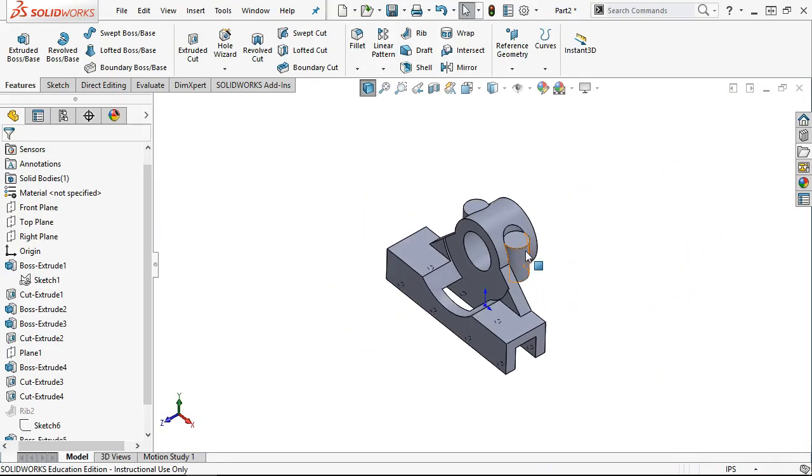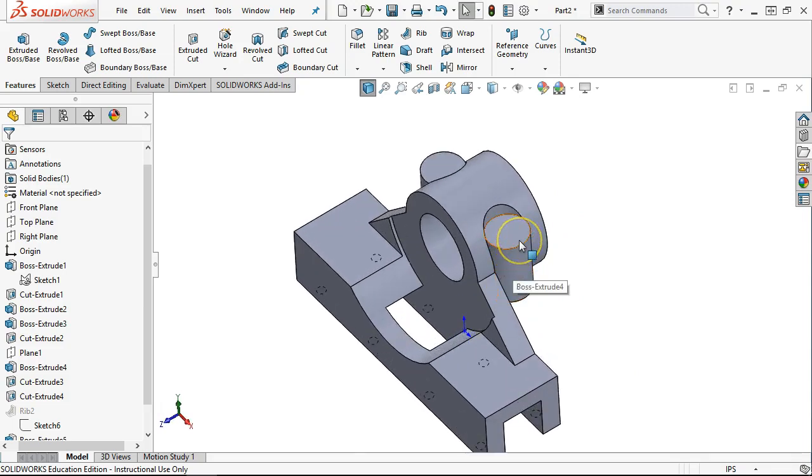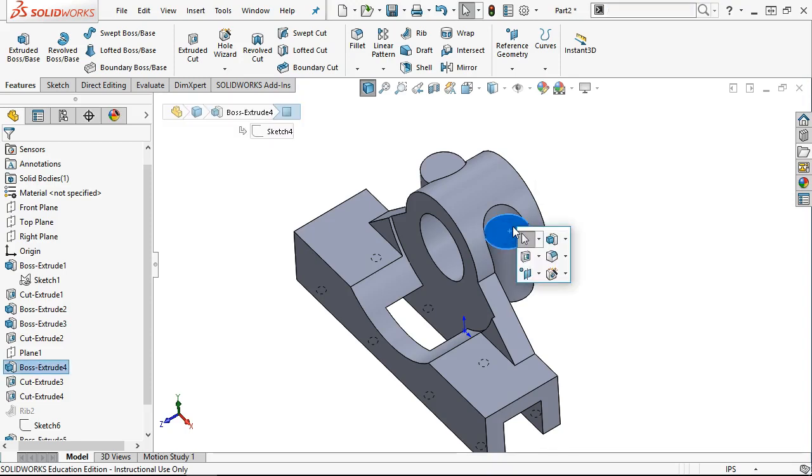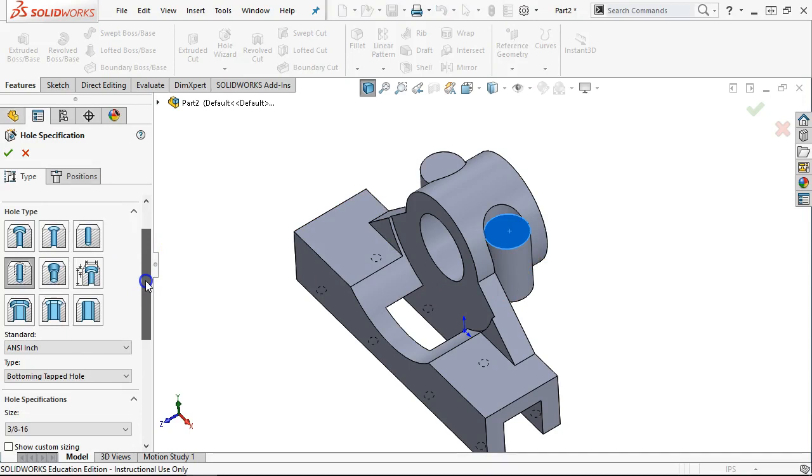Have that. All right, so we're going to see what we can do. And I'm going to try to put the spot face in first. And actually what we might do, this would be easier just to generate the 2 cut extrudes rather than trying to force it in with the hole wizard. But get into that mindset of making the hole wizard work.